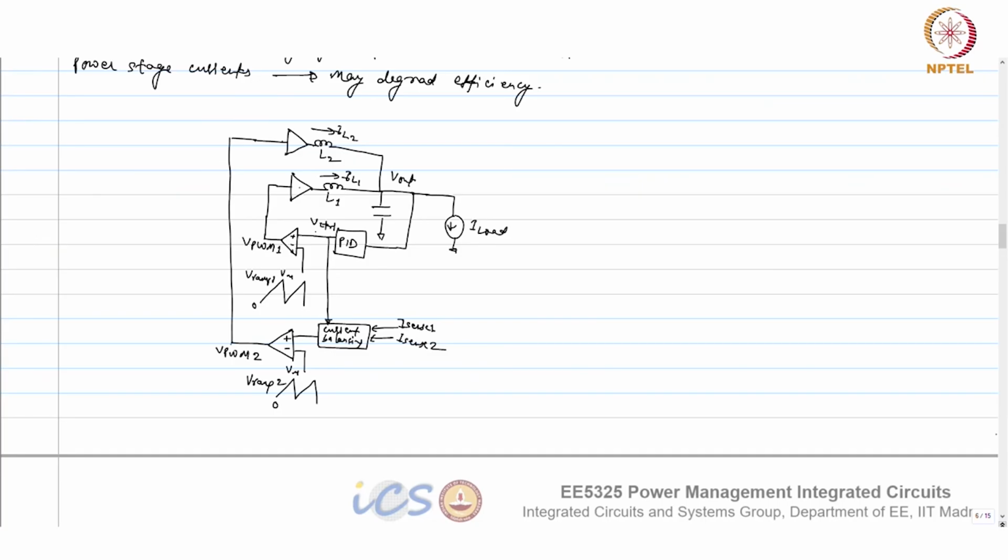But in the time-based design, we don't get that problem actually, because you tap the phases and they are already matched. The delays will cause a mismatch. Let's say I have 5 delay cells in the ring, so it's a 5 phase. I can tap 5 phases from there, but ensuring each delay cell is exactly the same or matched is very difficult. So the phase to phase mismatch may be there. That may cause a difference in the duty cycle, multi-phase.